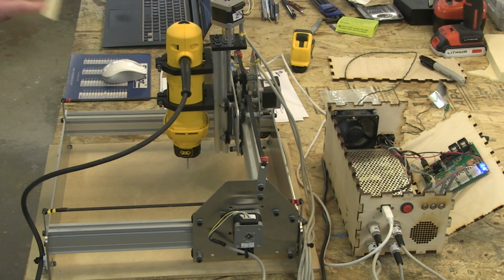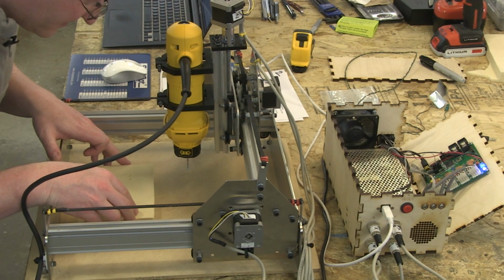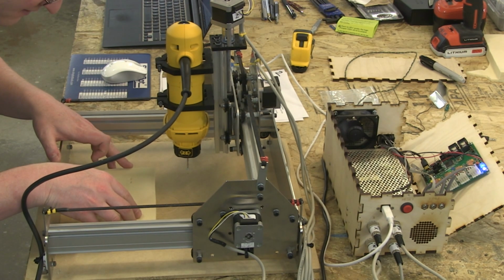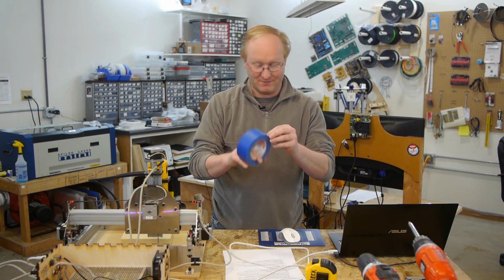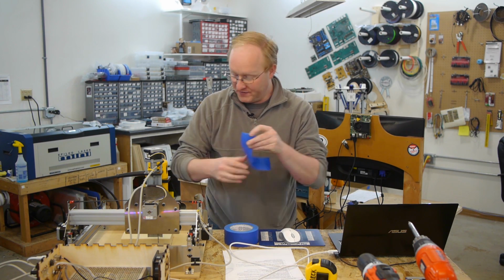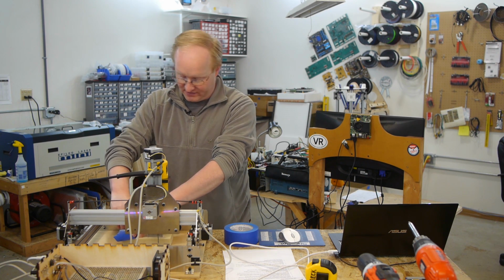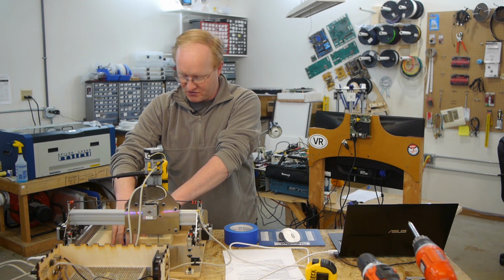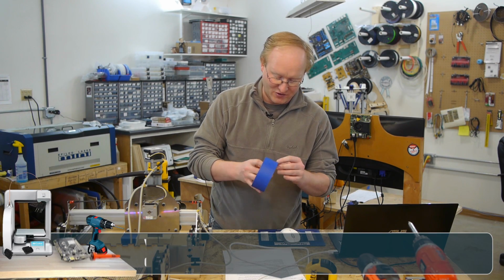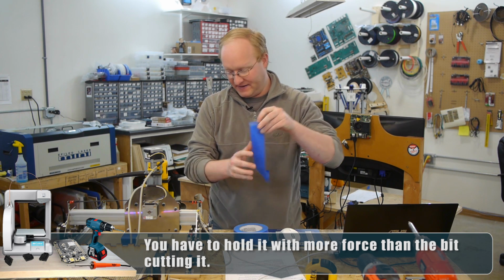Clear, all right. Now here's some engineering foam that I'm going to use. I'm going to put it right in the middle. Now, one of the most important things with mechanical CNC is holding your workpiece in place. On my big CNC machine, I'll use screws, or there's a vacuum feature that it has. This is a little bit more limited.